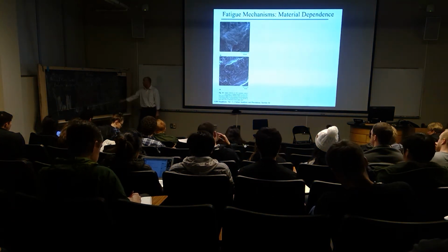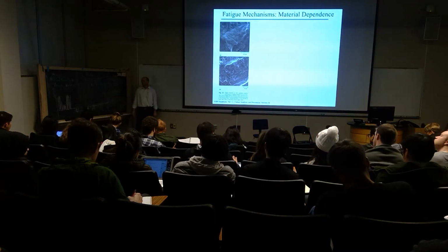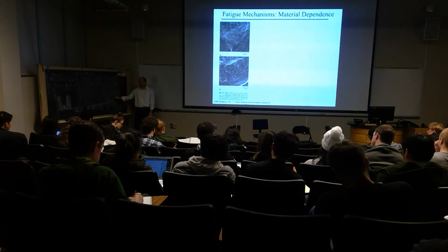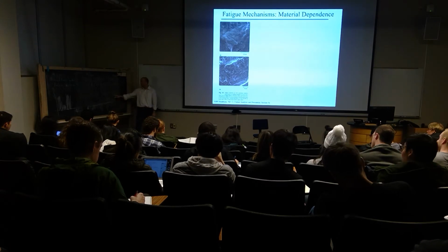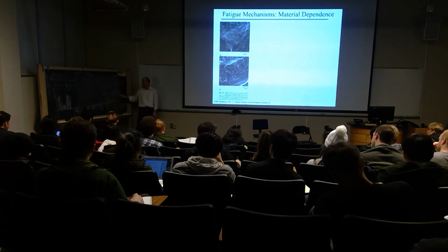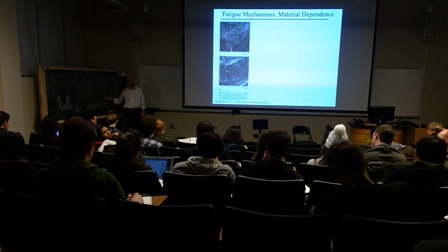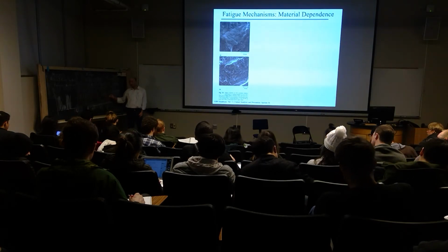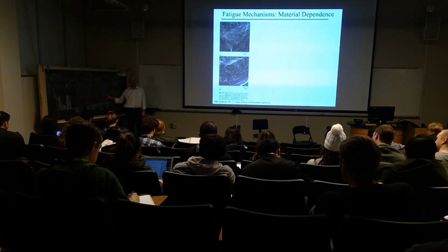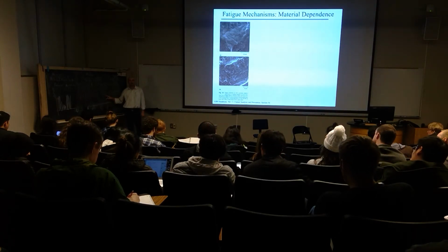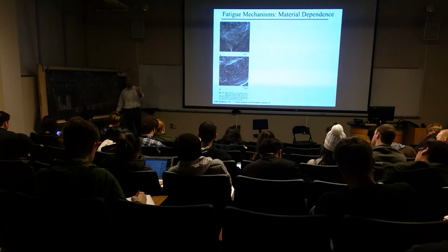So I'm thinking about this magnitude as a function of this that's taking place as the growth, the driving force in our crack extension process. Delta K can change with extension, and delta K is changing because as this increases, the delta K value increases as well, right? It increases from the point where the crack started to the point where it went unstable.